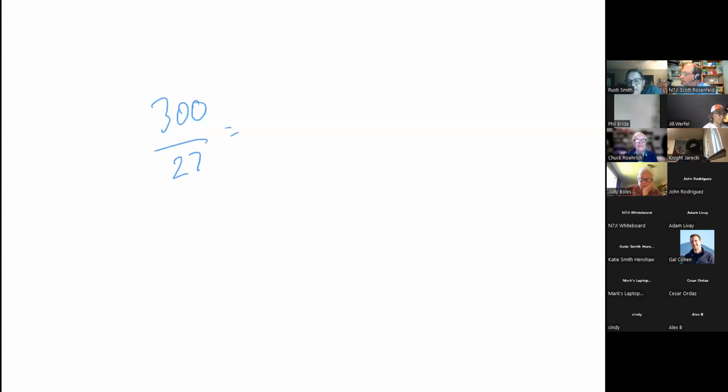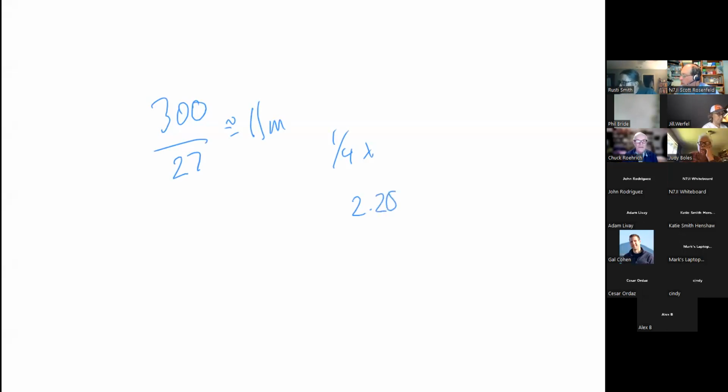Wait a minute, say that again separately. Here, I'm drawing it. 300 divided by 27 is about 11 meters. And we want a quarter wave whip. So a quarter wave of 11 meters is about 2.75 meters. And take that times 39.3 inches.